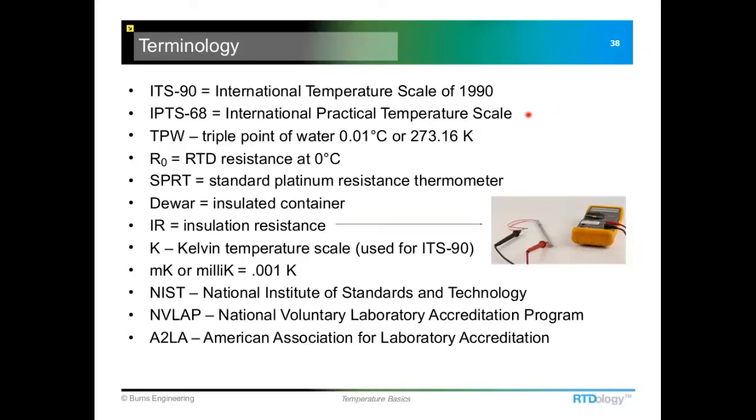You'll be able to take these calibration coefficients, which are the Calendar Van Dusen, or CVD, and plug those into your instrument. And that way it will match the exact resistance temperature characteristics of the probe to the peripheral, and you get a lot better accuracy that way, because it takes that interchangeability number that the manufacturers have to meet, takes that out of the equation almost completely.